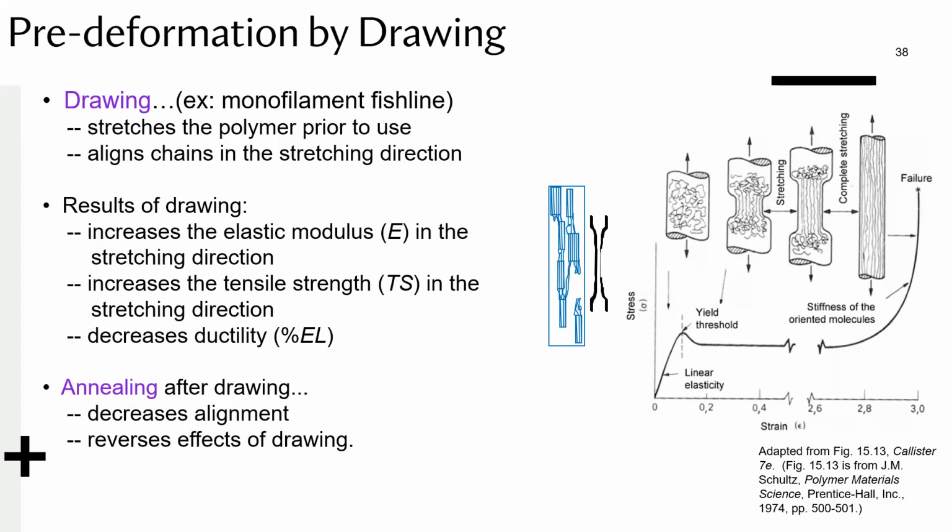What this slide is telling you is that you can actually utilize this change of behavior or mechanical performance in order to enhance the properties of a material. So, for example, you saw how when you stretch these, the slope can actually change in a lot of these materials. You can see how these long chains can get aligned into more of an aligned and crystalline structure out of that rather random amorphous state.